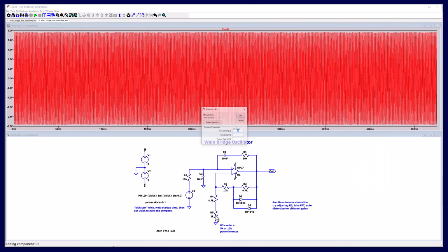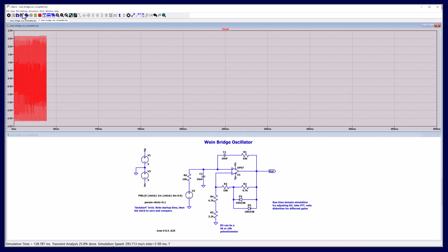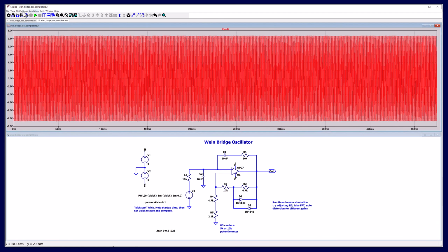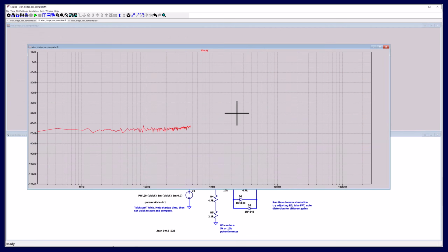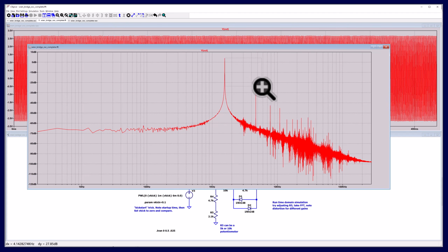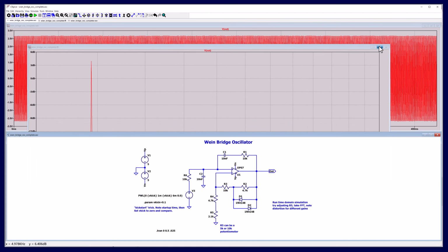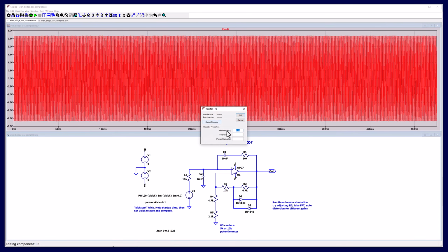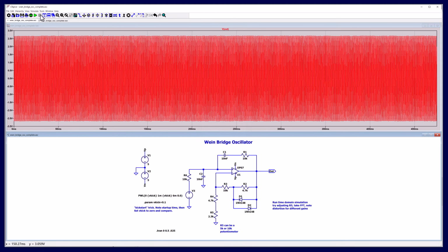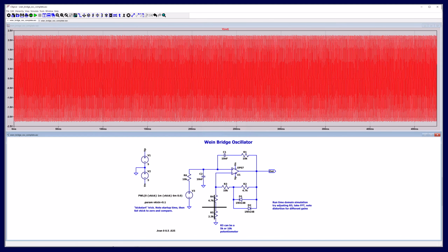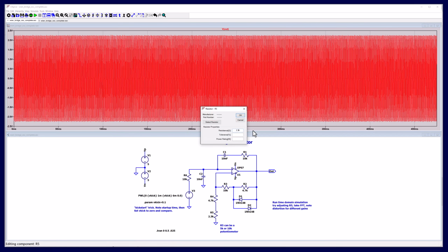Now let's reduce the gain a little tiny bit more. We'll go 2.1 and then run again. Okay, and then view FFT. All right, so now if I look at the delta, I'm at about, oh, still 27 dB. Okay, so maybe we are approaching the limitations of this circuit here. I'm going to try one more try here. So let's really interpolate. Let's go 2.3K. Still oscillates.